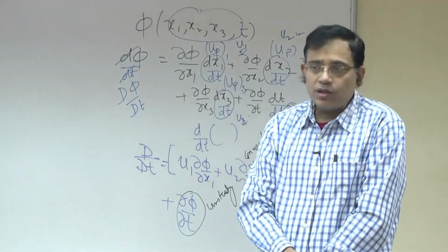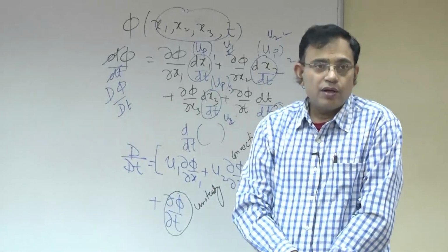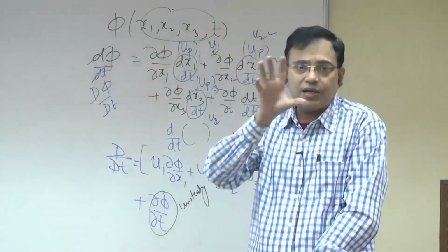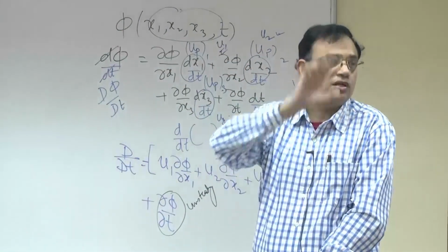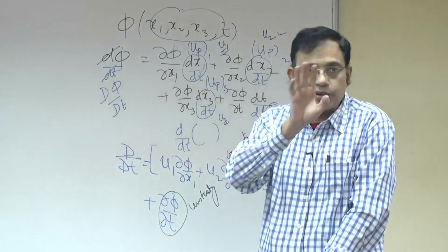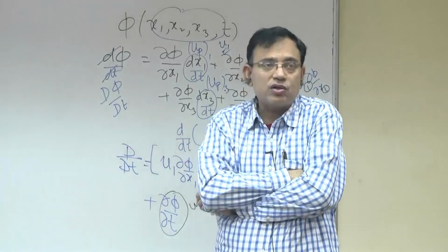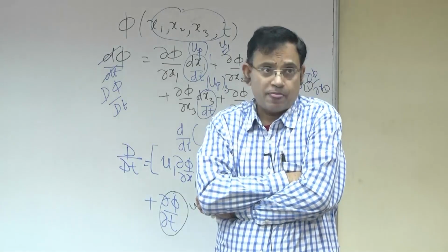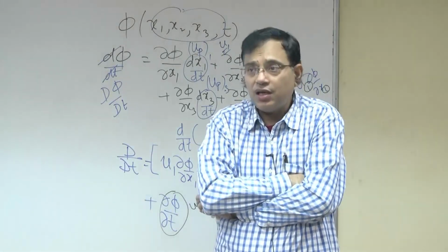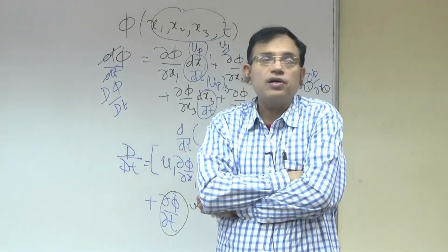Just to make you alert, there is a difference between incompressible flow and incompressible fluid. When you are talking about incompressible flow, you are talking about kinematics: there is a volume, and that volume does not change with time. It does not talk about any property, whereas incompressible fluid is talking about the property density, and whether that density is a strong function of pressure or not.